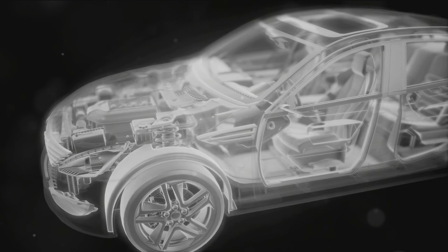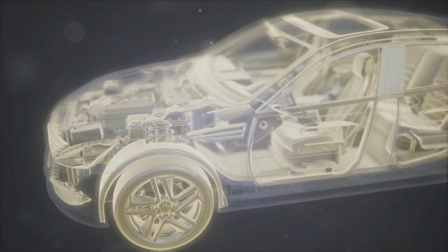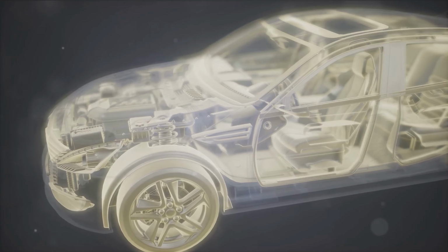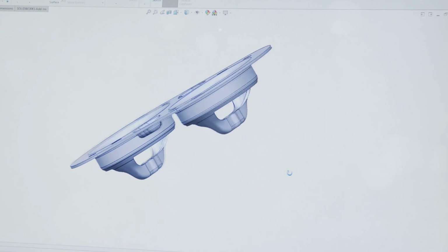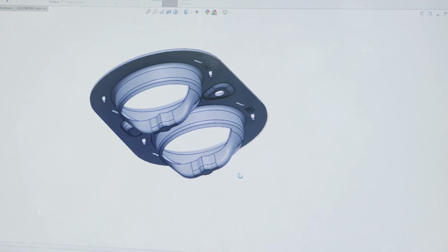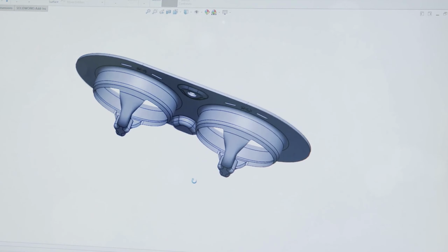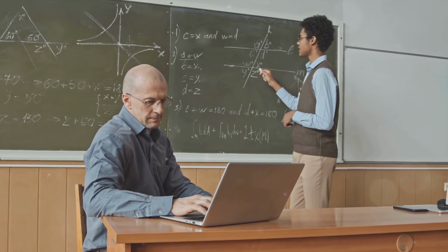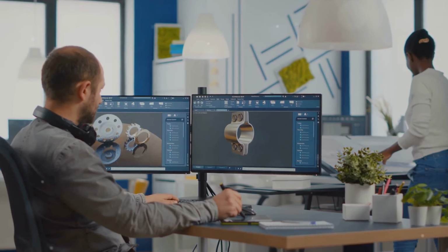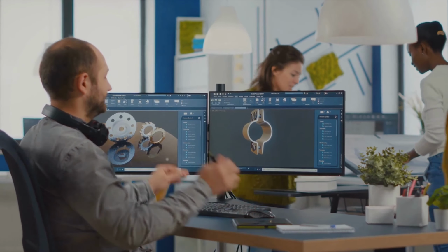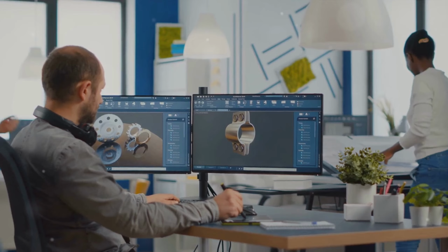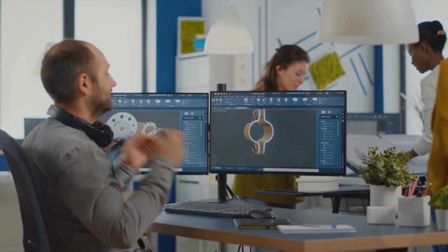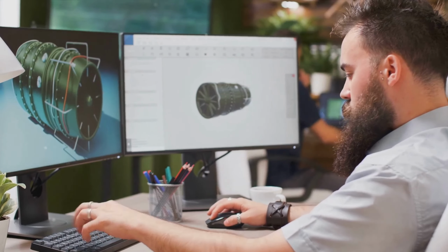The MRF model, on the other hand, is a steady-state approximation technique used to simulate the effect of rotation. In this model, the computational domain is divided into stationary and rotating zones. The rotating zone contains the rotating parts and the fluid within it, while the stationary zone contains the rest of the domain.